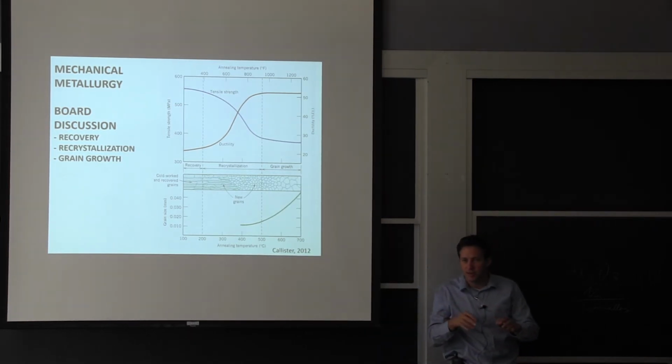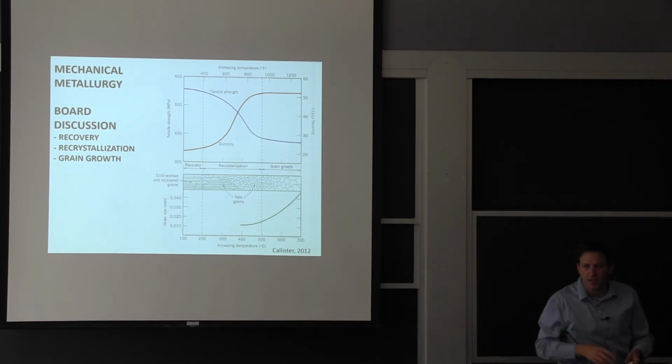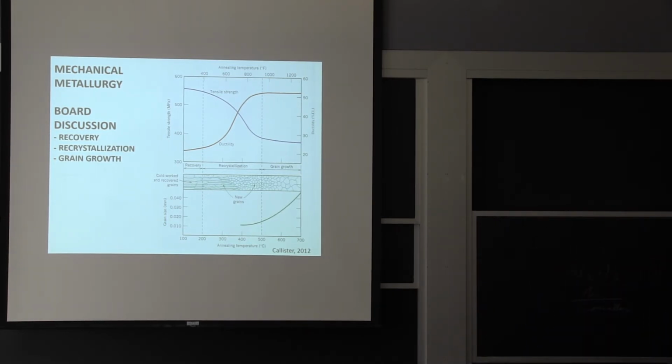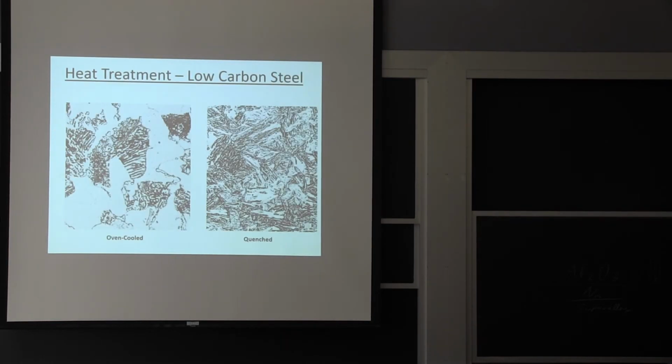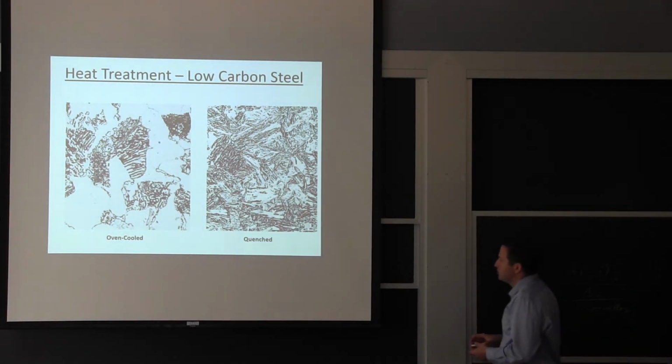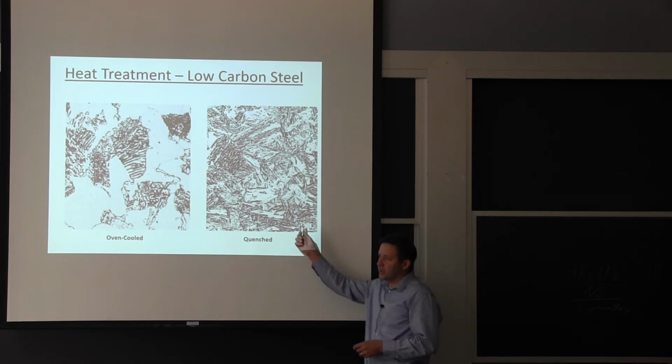We're not talking about electrodeposition or forming nanostructured material here. This is conventional processing. You can make ultrafine grains through this process that would be less than a micrometer in size, but a lot of times we're talking more like 10 micrometers for steel, and even a little more for aluminum and copper.